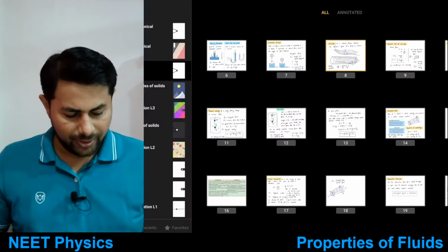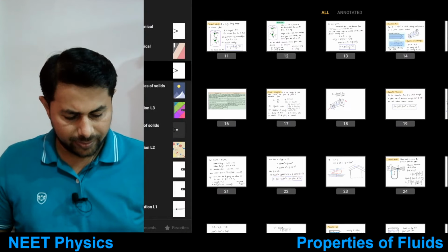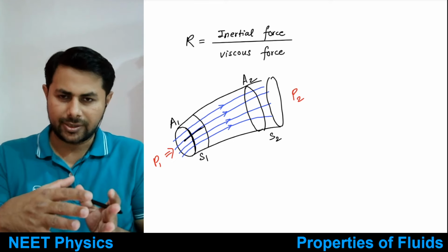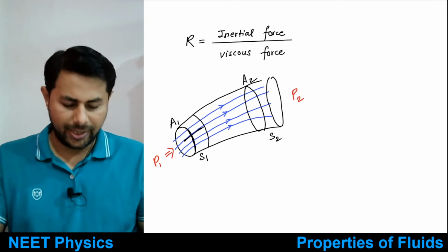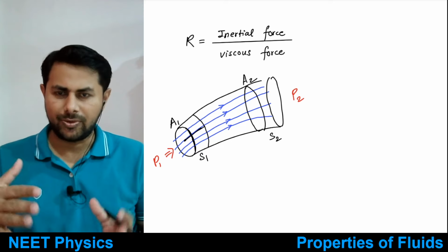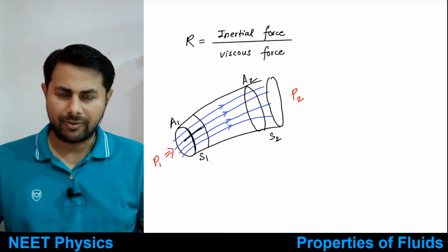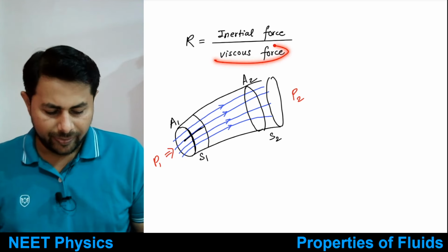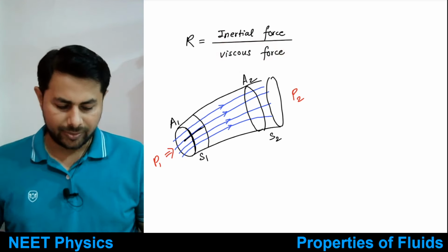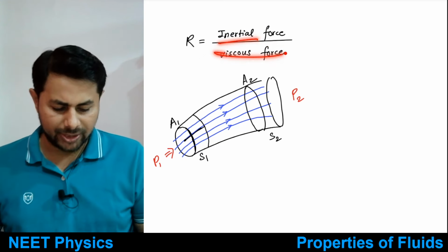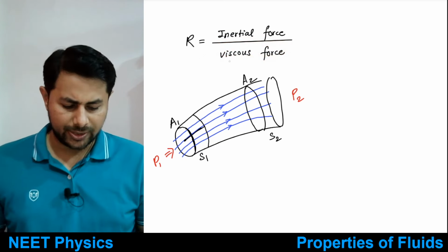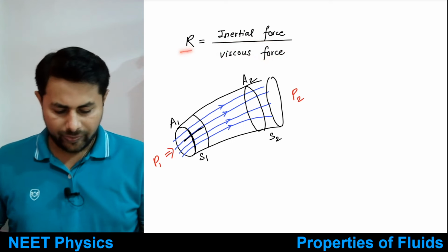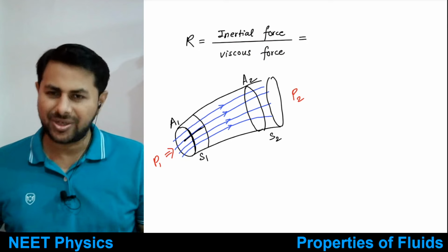Okay. So the viscous force opposes the turbulence, right? It won't let the fluid flow in any direction with very high velocity. It restricts the velocity, and that's why it's in the denominator. The inertial force is in the numerator; the viscous force opposes the turbulence, that's why it is in the denominator. Okay, so now there are a lot of calculations in this.